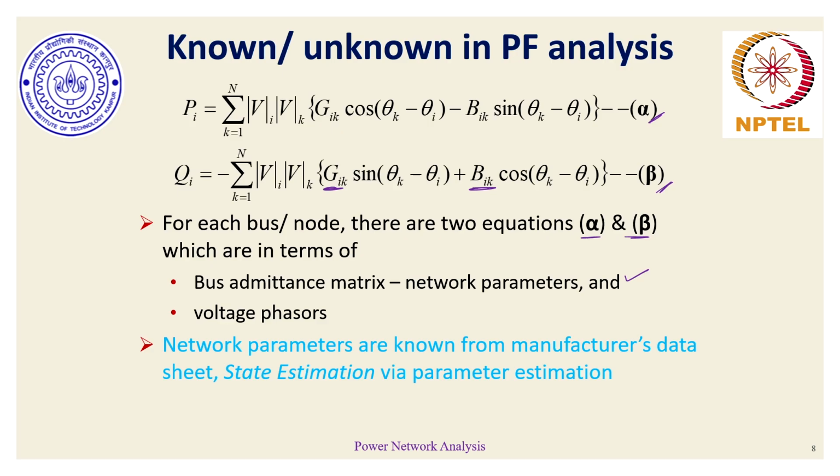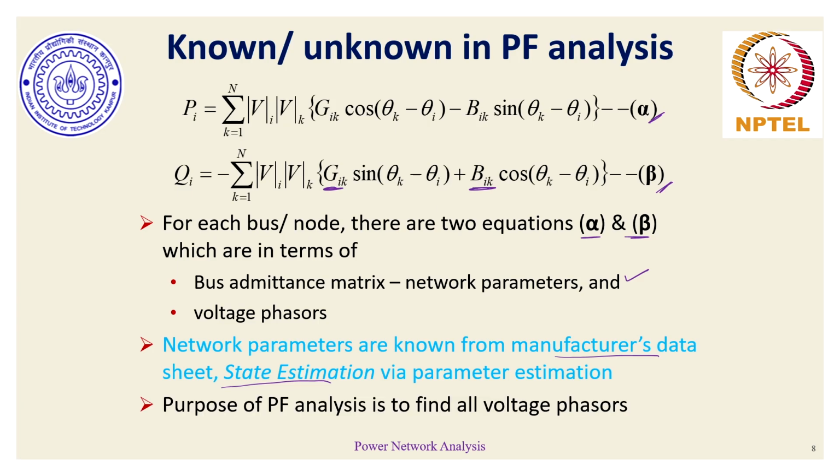The parameters are known from manufacturer data, and there is an optimization exercise which also helps in knowing the network topology and states, which is known as state estimation. And the purpose of power flow is to find all these voltage phasors.